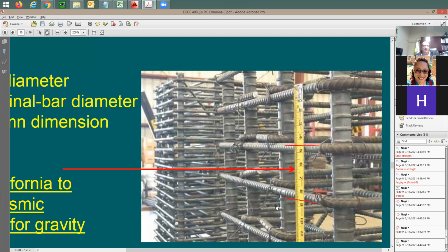Just imagine the person, you see all of these wires? It's gonna be like the tie wire. And here you see this is gonna be like the cross tie. This is gonna be like the main tie. And this gonna be here the cross tie from both sides because of the spacing between the vertical rebars. And just think about the person who's gonna put his hand here to tie all of this and to work in here. Now, how about here? How would you do it? It's gonna be kind of impossible. It's gonna be real tough.